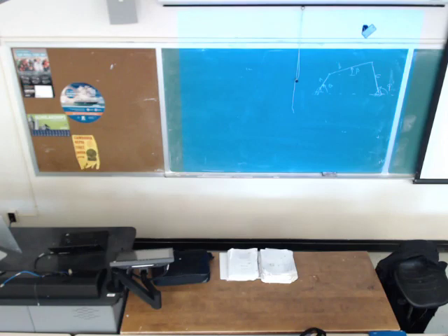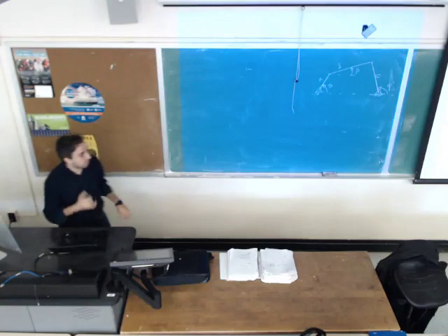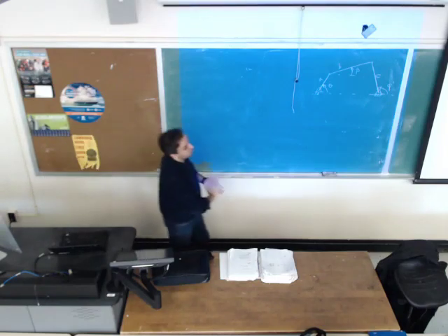And we would like to have 3 precision points. When x is at 6 degrees, we would like y to show exactly sine of 6. When x is at 45 degrees, we would like y to show sine of 45. And when x is at 84, somewhere here, it should show us the exact value for sine of 84. I picked some random numbers just to show you it can be any desired precision point. So this is what we want to do.